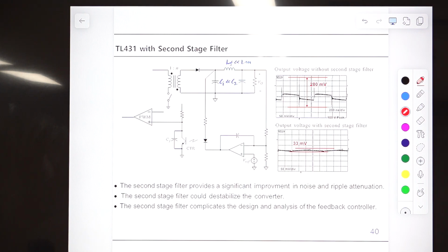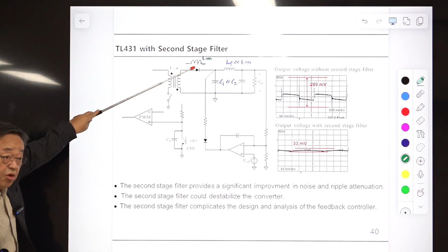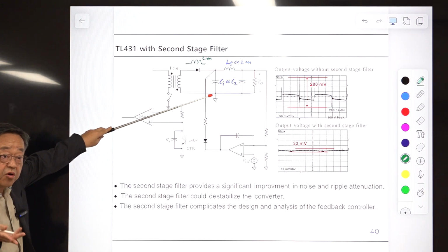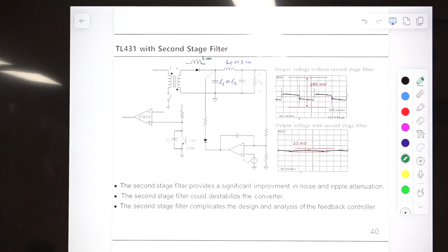This is a flyback converter. So there is a filter. This is the magnetizing inductance of this flyback transformer, LM. You are not seeing this. This is the inside of this transformer. But this works as the functional inductor in other converters. So assume this is an inductor, and this is the extra component you added. Okay, this should be very small, smaller than this magnetizing inductance LM.